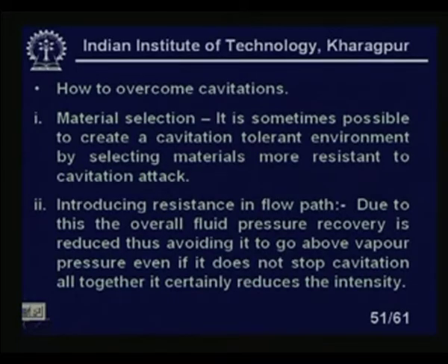Introducing resistance in the flow path, and due to this, the overall fluid pressure recovery is reduced, thus avoiding going above the vapor pressure. Even if it does not stop cavitation altogether, it certainly reduces the intensity. The intensity of the cavitation will be reduced.